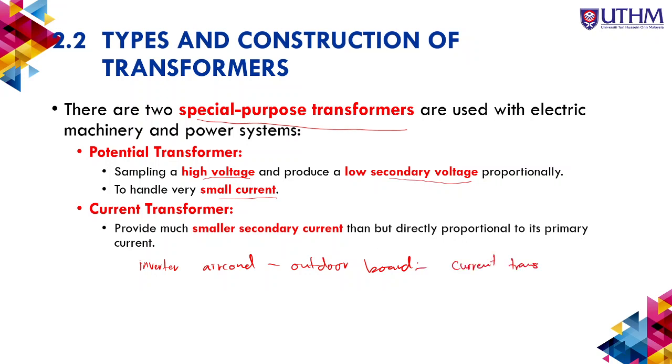Later on you can try, because previously my aircon also broke down, and once I opened the board, I could see the current transformer was what they call an open circuit. Open circuit means there is a wire that is disconnected. So we need to change the current transformer.